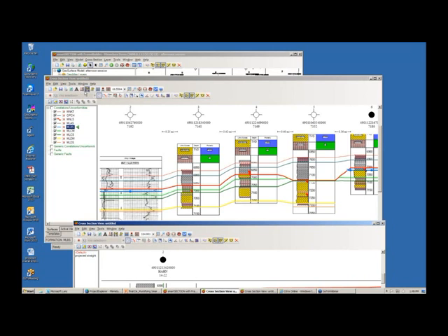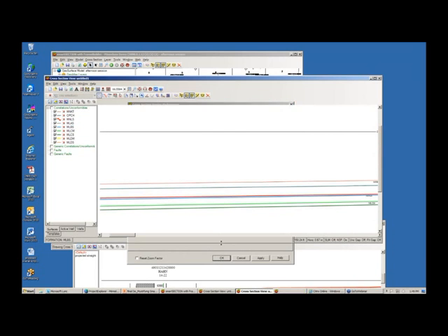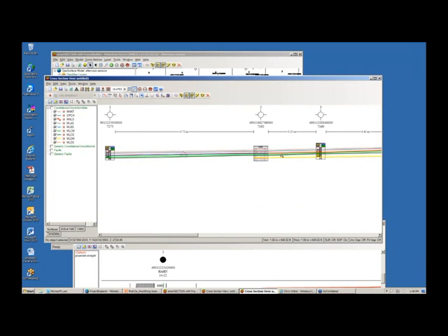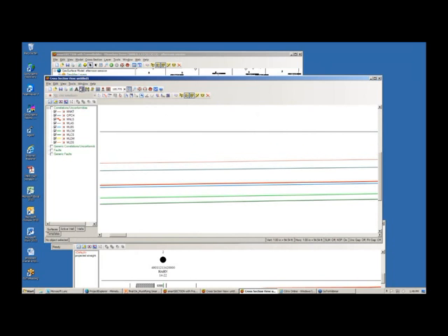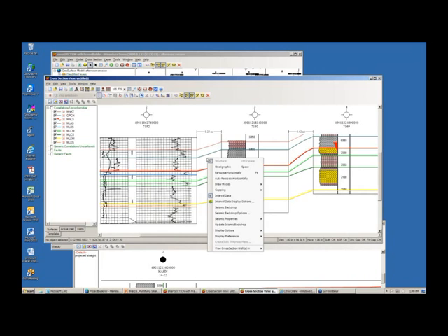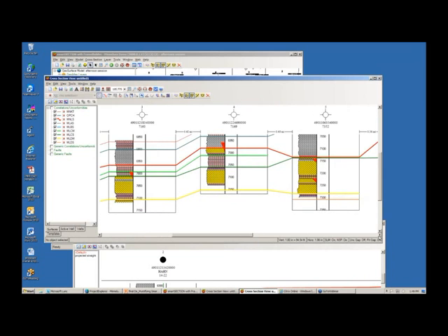If I were to proportionally space this specific cross-section, you wouldn't even know that there's undulations going on here. I'm just going to proportionally space this cross-section for a moment and zoom out so we can see them in their kind of true position. You can see that things don't look abnormal, but let's just say you wanted to see a real purely straight line. You're correlating. You don't want all this inner well business going on. Let me go back to my equally spaced. I can just simply do a right mouse button, draw modes, and choose straight line mode, and then you are going to get that classic traditional X section look.